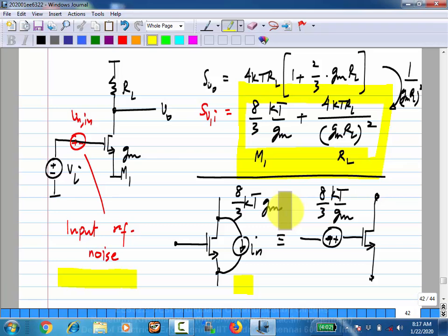Yeah, correct. So basically, in any model, even in circuit models, some things will work up to some extent. To what extent they work, if you want to figure out, you will have to go deeper into the science behind it. In that particular case, I showed the inversion charge mainly to show that when VDS equals 0, it looks exactly like a resistor. It is in fact like a resistor. You have charges which are colliding with fixed atoms and so on. I don't mean to discourage anybody from studying device physics, but to use the model, you don't need to know it.